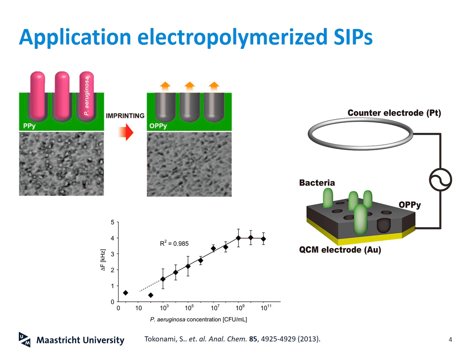So what happens in a QCM is you use a gold electrode and you deposit that onto a quartz crystal, therefore quartz crystal microbalance. And these quartz crystals are piezoelectric. This means when you apply an electrical field over them and a changing alternating current, they will start vibrating. And they will do so at a certain frequency that is constant and is called the resonance frequency.